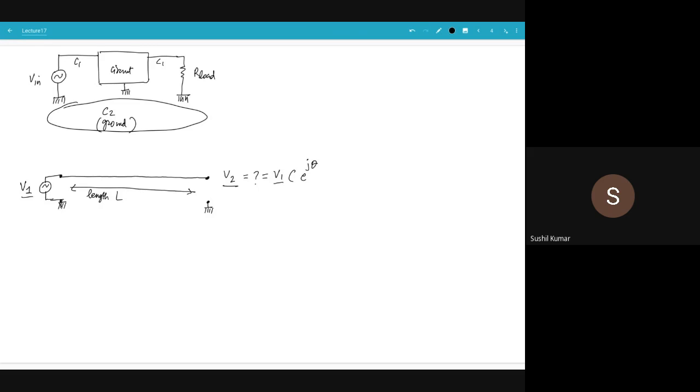We ignore those wires. In your simulations, you can make those wires as long as you want, as short as you want, and not just simulations. If you're actually building the circuit on a printed circuit board, do you ever worry about whether I should pick a small wire or a long wire? Not much, right? And the reason is that wires don't matter. The voltage from one end is the same.